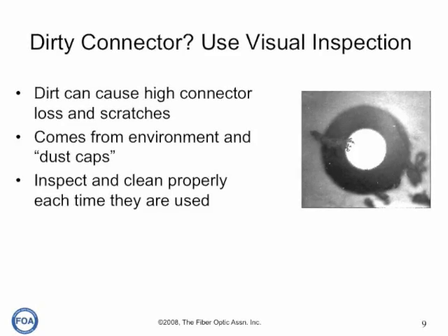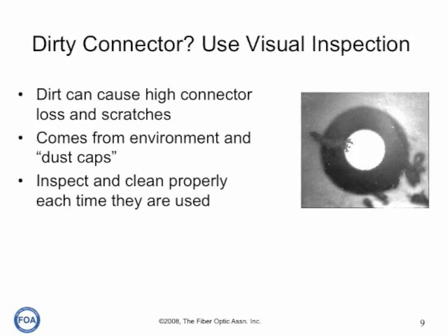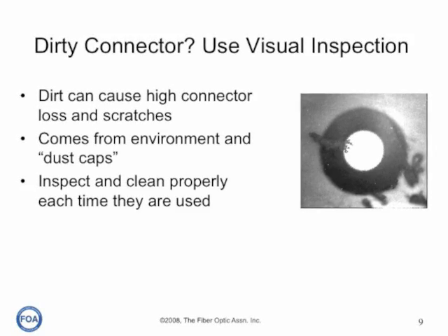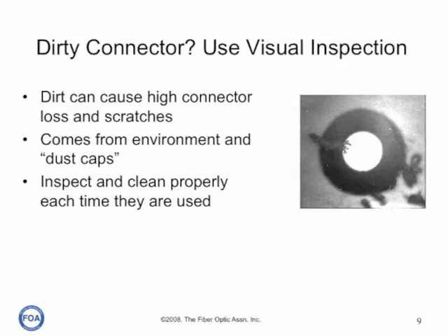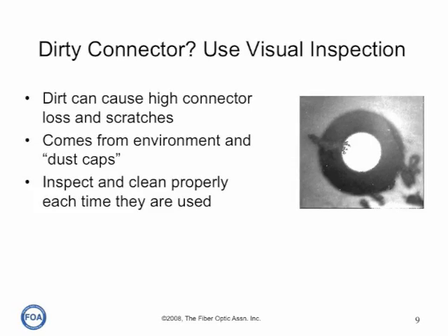Visual inspection will show you dirty connectors and show you how well you've cleaned them. Look at the size of the piece of dirt on this connector. It's almost as large as the 62.5 micron core of the multi-mode fiber. And there are other large pieces of dirt near the end of the connector.